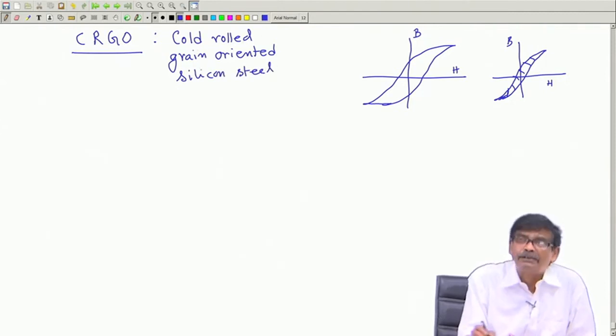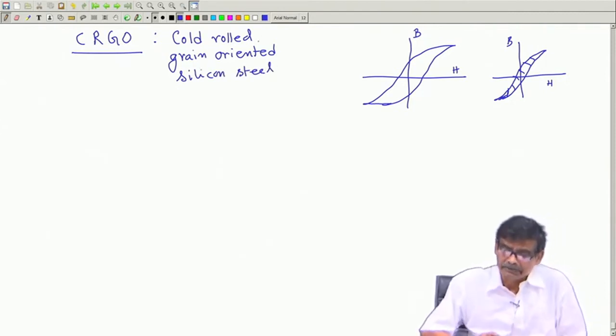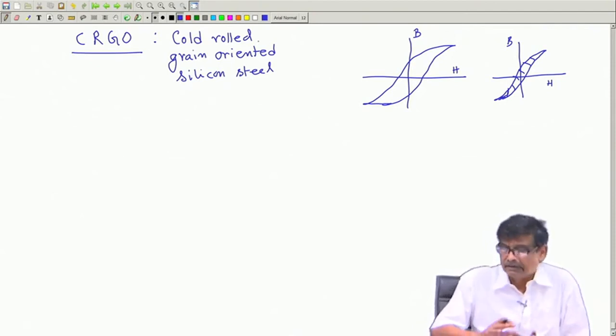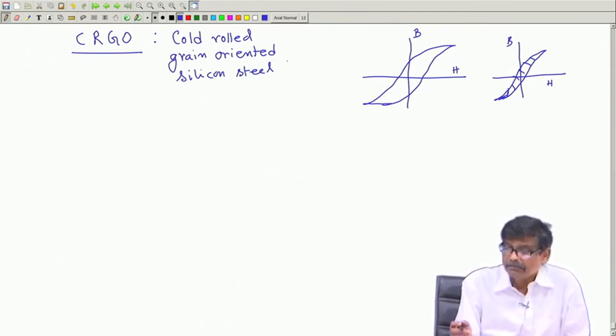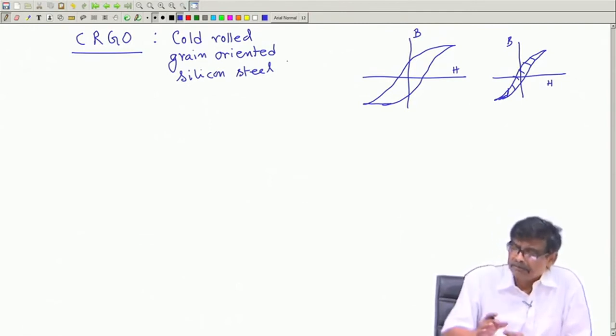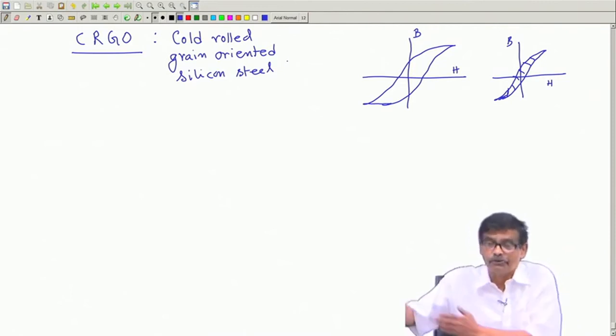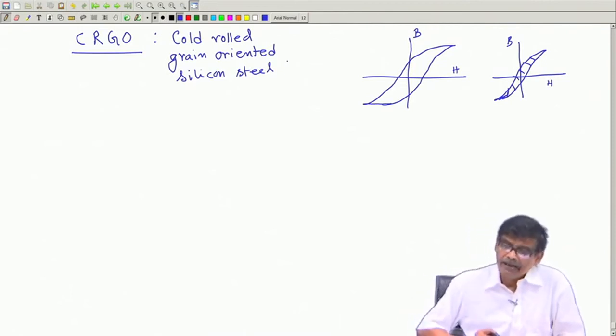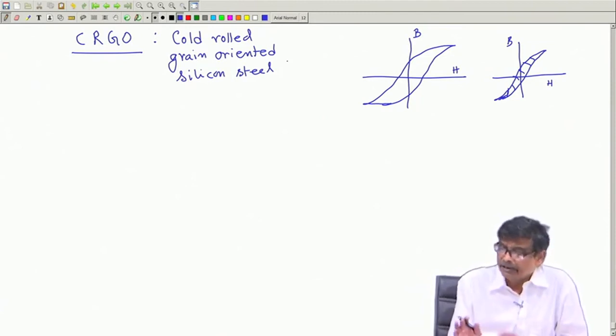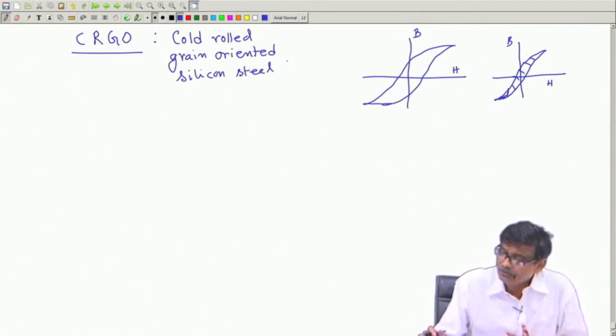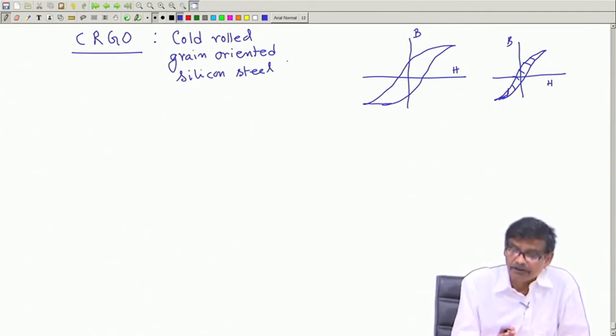This is some metallurgical process, that is, you treat the iron laminations in a particular fashion, so that the grain oriented, meaning the tiny magnets, are locally in some groups oriented already by that process when you roll this material. Anyway, we will not go into that, but the idea is to see that the area enclosed by the BH curve will be small.